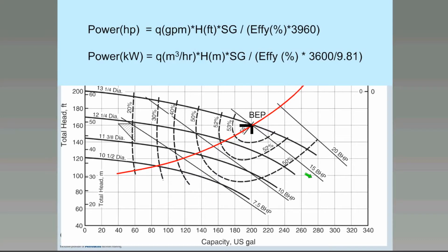Sarah, that's a great question. To answer your question, and if I can read into it a little bit: how far can you extend beyond the right-hand side of these curves? How close to the vertical axis can you operate? What is the operating map that you can utilize for your pump? What's that defined by? Vibration is a big problem in this process. As you get further and further away from the best efficiency point, then vibration will increase. There's also the consideration of minimum flow, and over on the vertical axis we see minimum flow.